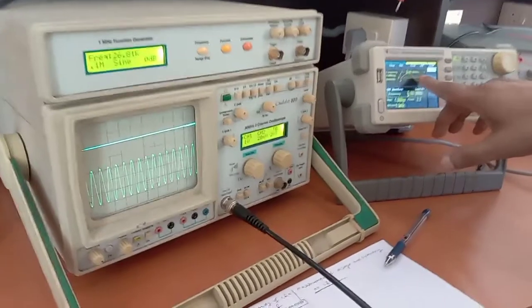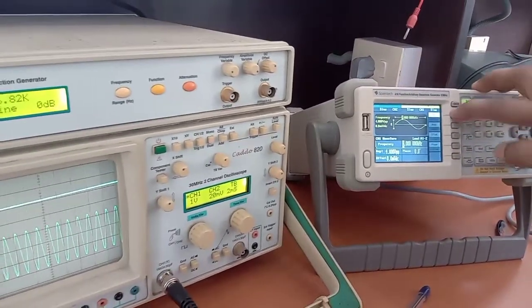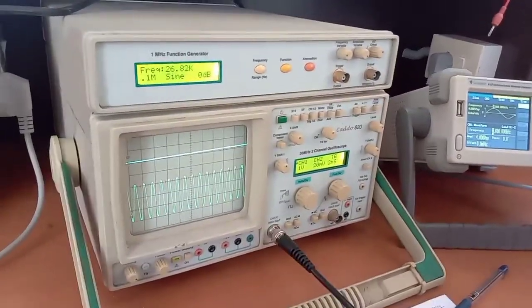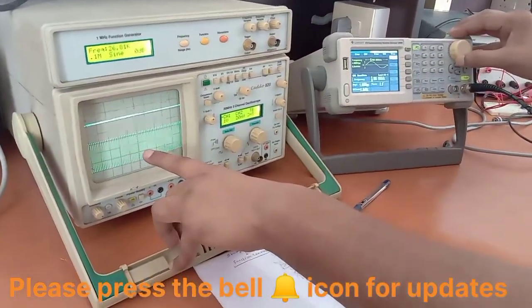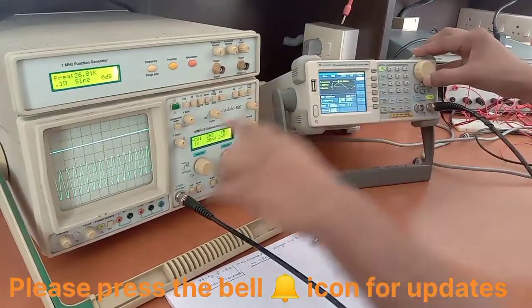Now, the frequency, this is frequency. We can change the frequency. So we have to go to the frequency tab, and then we can change the frequency here. When we change it, the output will change. So this is channel number 1, and the output will change here also. You can see the output is changing, the frequency is changing as we change the frequency here. So the frequency is 1 kilohertz.